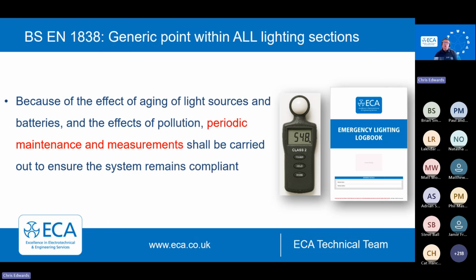This is another generic point, again, not necessarily specific to 1838, it's across all of them, and they're hammering home this point all the time, that periodic maintenance and measurements with regard to verification are required, because there's a recognition, of course, with emergency lighting, like all systems really, that batteries decline over time.